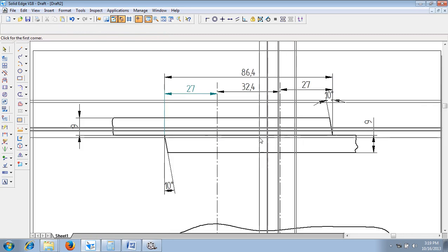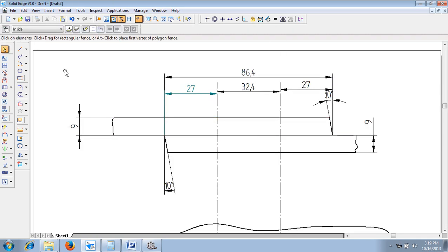Then how are we going to get a front view? Let me show you the construction of the front view. Now we know that starting from this position, this thickness is given as 0.8 into D. What is D? 18 millimeter. So 0.8 into 18 millimeter has to be measured in this direction. And what is the height? Height is given as 0.7 into 18 millimeter, that is 12.6 millimeter at an angle of 90 degree. And like this you construct the required rivet head constructions for the snap headed rivets.